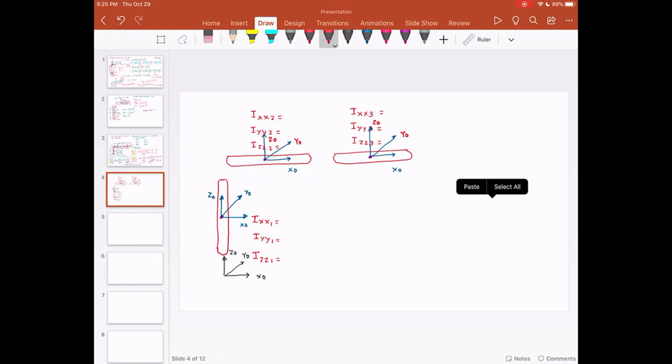good catch. So you need to replicate the coordinate system, this zeroth frame, at the CG of each link. And based on that, we need to find the moment of inertias. So I'm gonna write the moment of inertias, and we are going to assume a slender rod, which means the length dimension is the most predominant dimension.